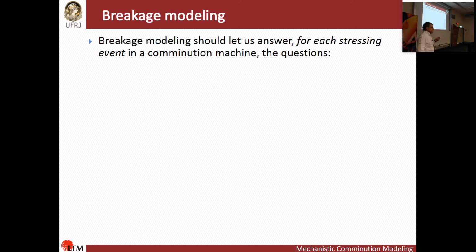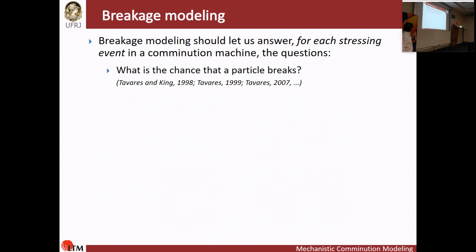In order to understand what we need to characterize when we model breakage to this level of detail, I think it's educational to see that, in the end of the day, the model has to be able to answer these questions. What happens if a particle is stressed under a given condition? What is the outcome of any event like that? Each single event. So, for instance, what is the chance that a particle will break at a given event, given the stressing condition, given the size, and so on?